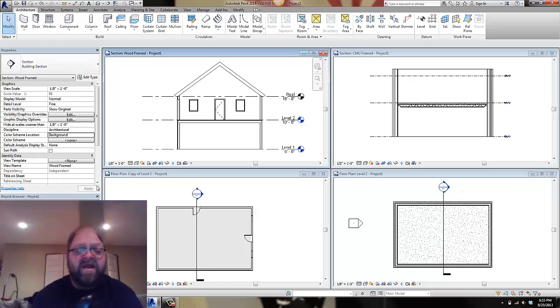Probably, but it's not going to have really good tools for doing that, because it has good tools for building buildings, which are not this small, and aren't usually this curvy. So the tools that Revit gives you to make a shape like this are a lot harder to use because you don't have those general tools. You have tools like walls and doors and windows, so you have to figure out some way to get that shape out of it.